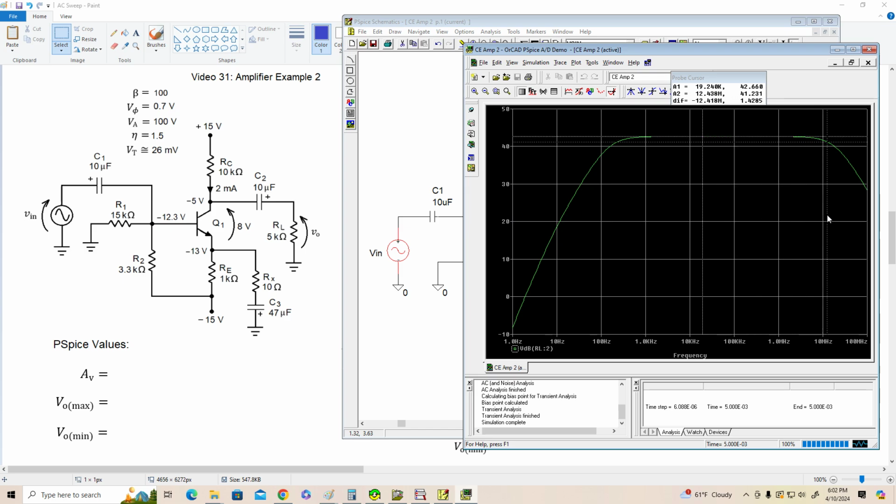And let's see, 3 dB is occurring at about 20 megahertz. So this amplifier ideally should operate well from around 100 hertz all the way up to 20 megahertz. Again, PSpice is assuming that we built this thing perfectly, and the limiting factor is the transistor itself. In reality, our wiring technique is probably going to cause the corner to be back around here somewhere.